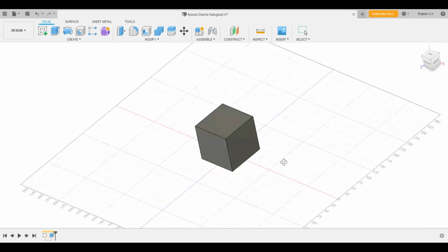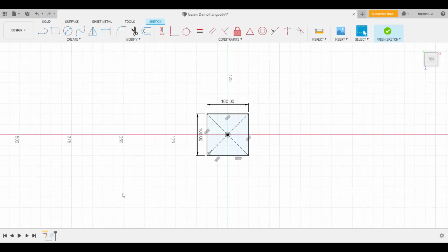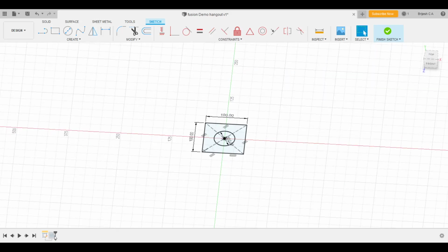Or I could go to the sketch that I initially created, and in the sketch itself I make a circle and then extrude the entire thing. So let's see all the three options. The first option is for me to go to the sketch and create a circle. So I have an option called circle here. Click on this, my circle. I want the dimension of the circle to be 50 mm, which is the diameter of the circle. Enter. Now I'm going to create, go to extrude,